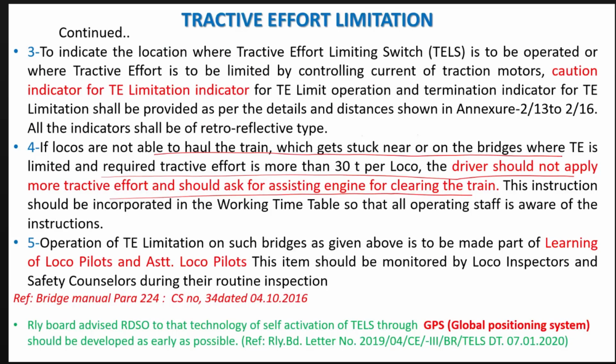this tractive efforts meter also we can see in the locomotive, it is very less. But when it is starting, the initial tractive efforts will be very high. That time only TLS is required. So stopping the train should be avoided on the approaches where the TLS is higher. Then the operation of tractive efforts on such bridges is to be made part of the learning of the loco pilot and assistant loco pilot. These are the given guidelines.